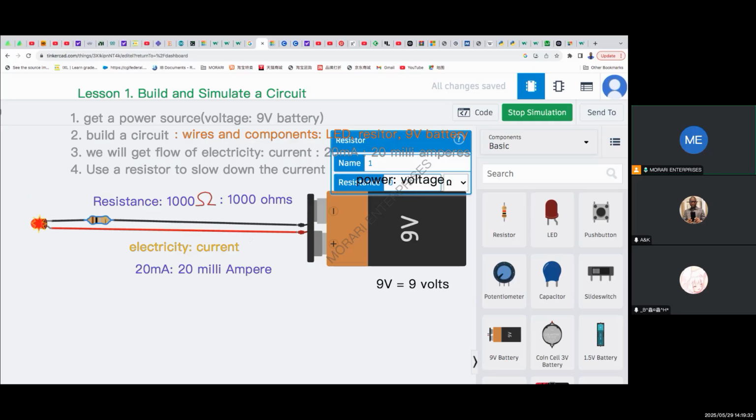I'm just explaining this. If we power that with 0 ohms, the LED will be broken. Yes, you'll get bad results. But if we put 1000 ohms to slow down the current, the LED will be like this. Arby, 1 second. You see the LED is not shining very brightly. Look at the LED, it's not very bright. So we can take down the resistance to 500 and you will see that it will be better than that. And if you go down to 400, it will be brighter.